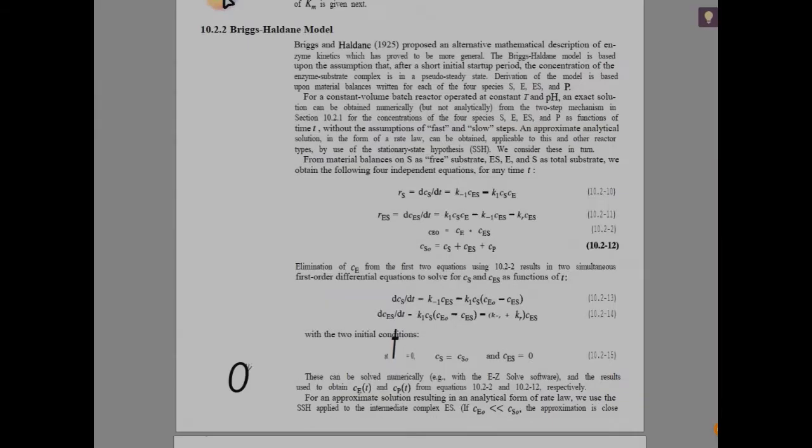The second question that has been asked is this: you have multiple reactions, like I have discussed, but the problem is that W over F naught is equal to the integral of dXA over minus RA, where minus RA is a single rate. So if you have two or three main reactions and you want to put in only one RA, how do you find the cumulative rate, or the summation of those reaction kinetics?